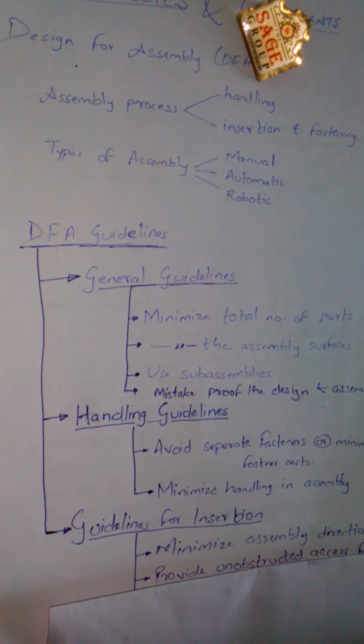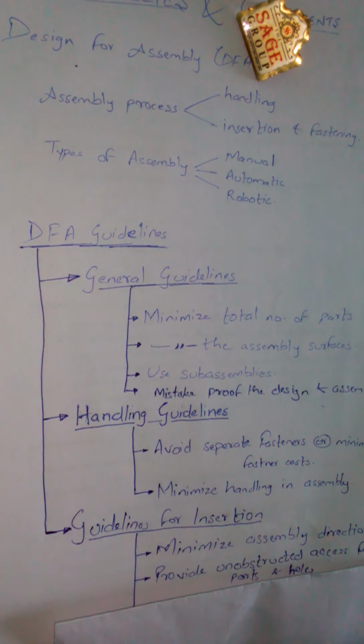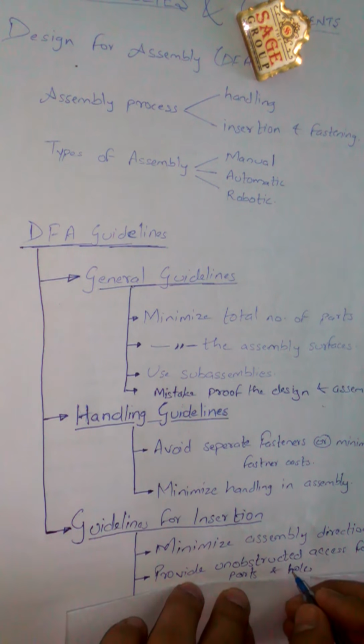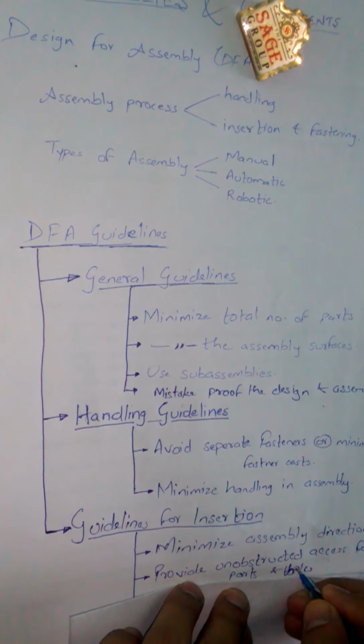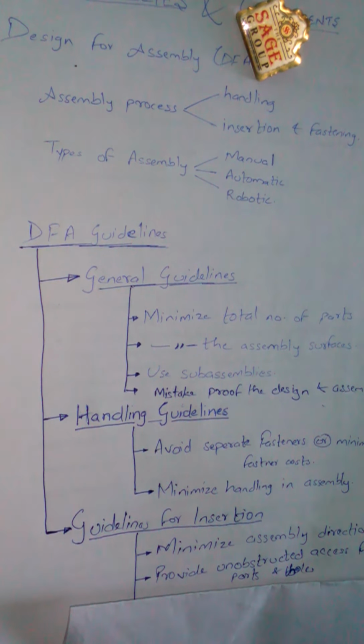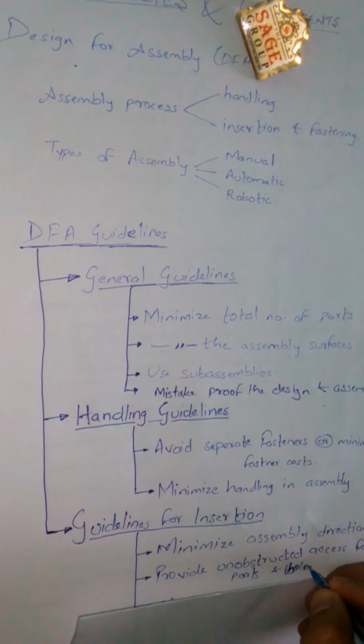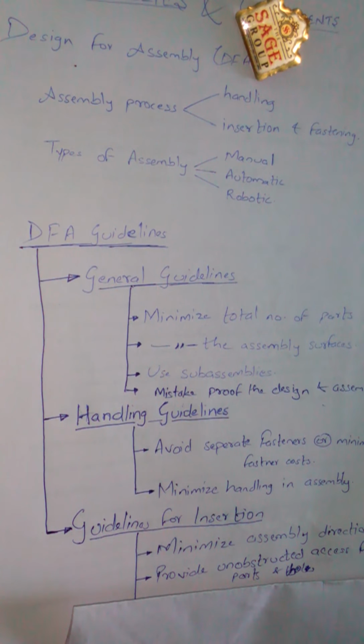Alright, the second point in this is to provide unobstructed access for the parts and tools. So not only must the part be designed to fit in the prescribed location, but there must be an adequate assembly path for the part to be moved to this location.